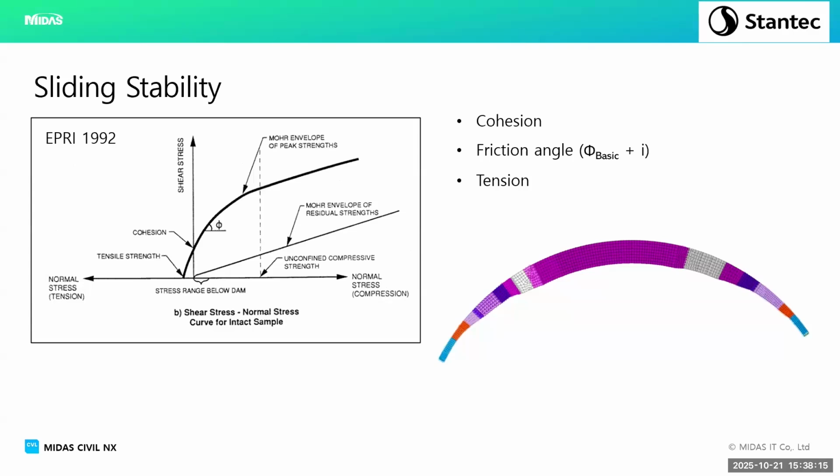that's what I'm talking about here, nothing else, is we want to capture our cohesion. We want to understand what our phi is. These are the variables. That will give us the first line. Then, as I said, because the interface between the rock and the concrete is often extremely competent, there is a direct tensile strength associated, and that's that blue portion there, which then we can define the other portion of our material parameter.